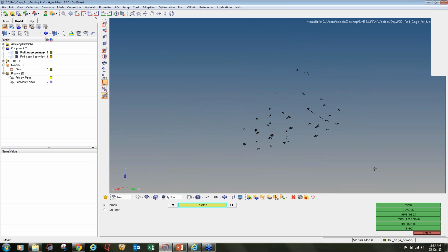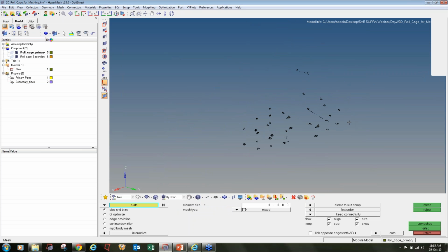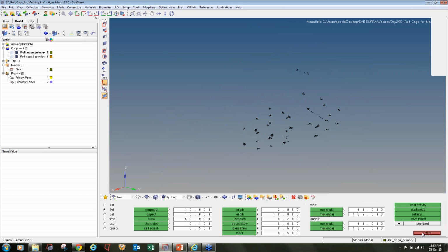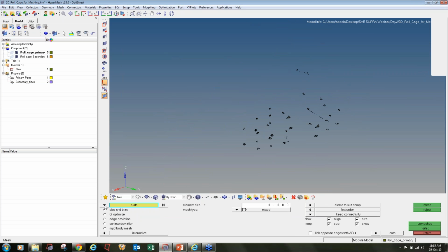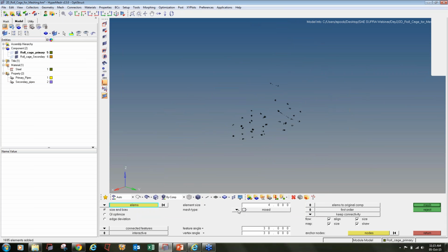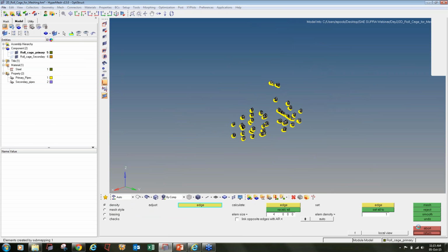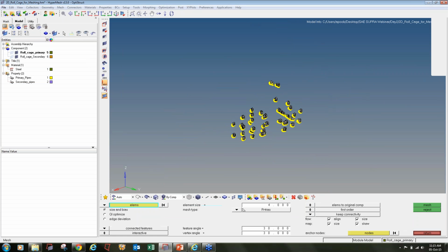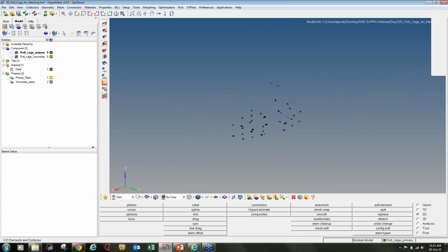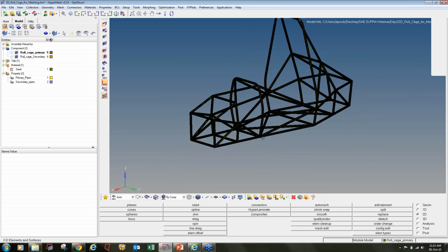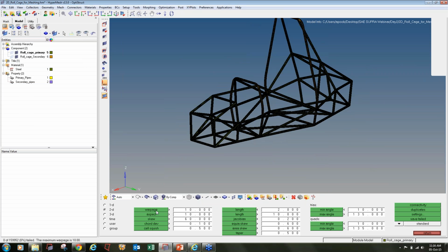To solve that warpage, there are many options, but the easiest way is to go to the 2D auto mesh panel. Instead of surface, now select elements. Select all those elements, select R tria and click on mesh. Then click on unmask. Again I press F10 from the keyboard and go to warpage. Now all my elements are passing. The next check is aspect ratio, and 18 elements are failing in aspect ratio, as you can see.